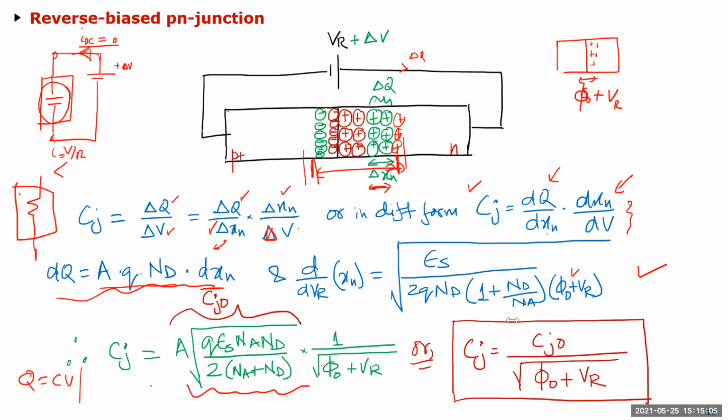Yeah, so I think Abhinav got it right. You apply the superposition principle to see if it is linear or not. So it is always good to know. I think you guys know from people saying that, oh, it is voltage dependent. Yes, of course it is voltage dependent because the capacitor is varying with your control voltage. But the more theoretical reason is that superposition doesn't apply to this, whereas for the oxide cap, it does apply.